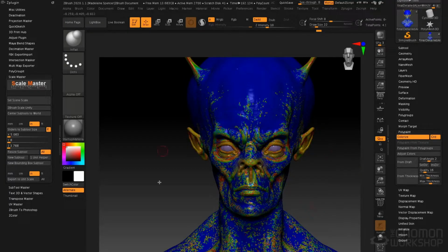And here we see the resulting map. We have an improvement now around the eye area and the ears. And as I said, anything that's just sort of these little spatterings of red, I don't worry too much about. It's only when we have a large region of red or yellow, that's when I'm concerned and I want to go in and manually check that specific portion of the mesh. So that is from thickness, and that is very important for when we're doing 3D printing.